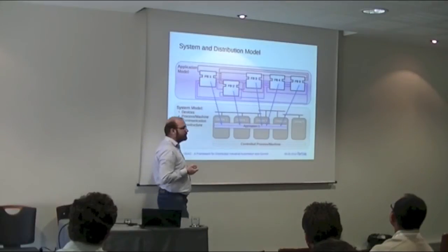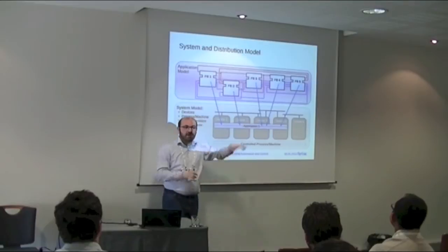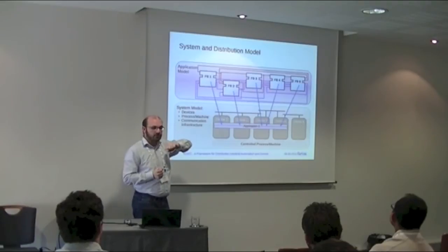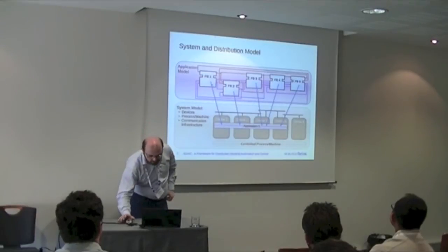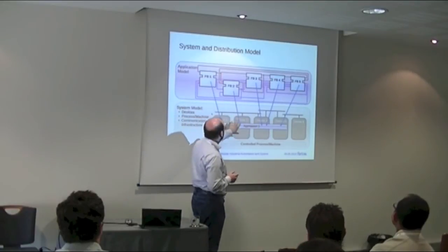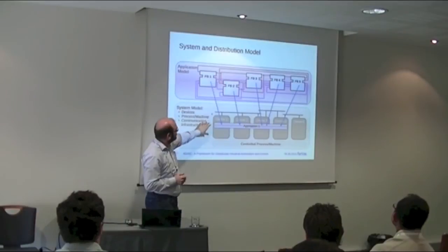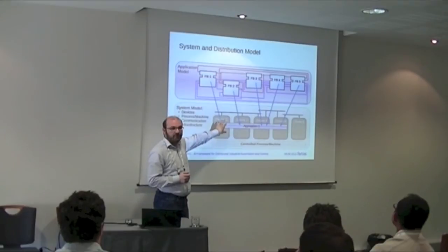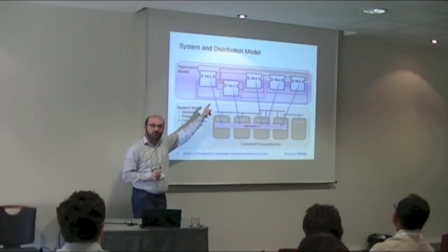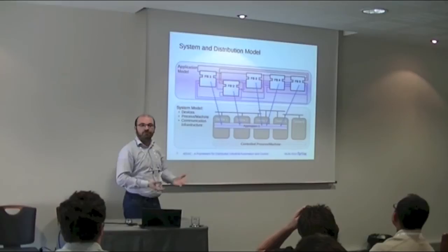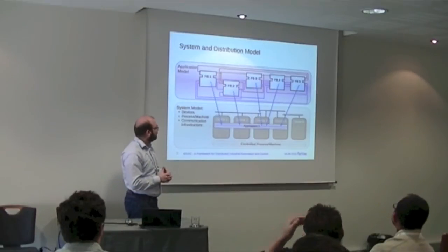Another point that is also interesting is, if you put now these function blocks, as I did, in different devices, we have now the problem that several connections are now broken. If you look, for example, where's my mouse, the connections here between function block 1 and 2, they are a set of event and data lines. And this means that you have to put here some, currently manual, I hope you can in the future also do this automatically. In the devices you have to then program some platform specific stuff. Still, this will not change the functionality of your overall application. It's just glue code, I would say, or platform specific code that has to be done.